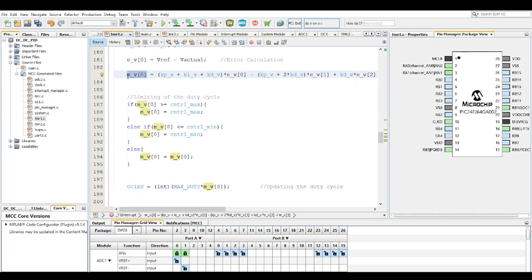There's a reason for that, because in the modules that I've done in the past, talking about control, we have always assumed that the maximum output is always 1. So I try to bring that same energy into the code, because I find that the code is a lot more stable when I make that assumption that this maximum value is 1. And this code is a lot more scalable that way, so you can use it on another microcontroller with a different PWM resolution, and you don't have to worry about changing these coefficients. You could just use literally the same coefficient. All you have to do is change the max duty cycle.